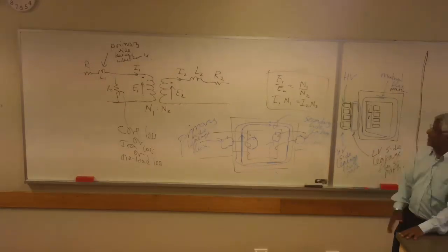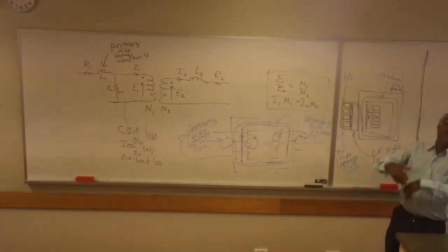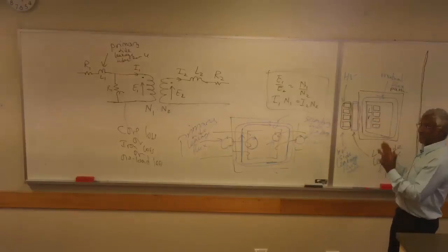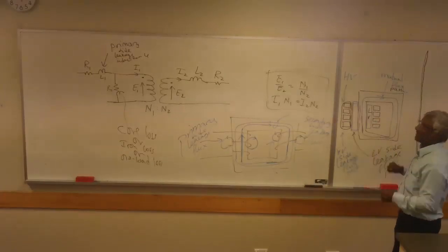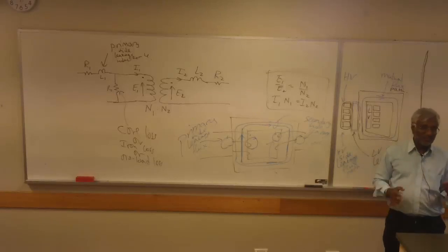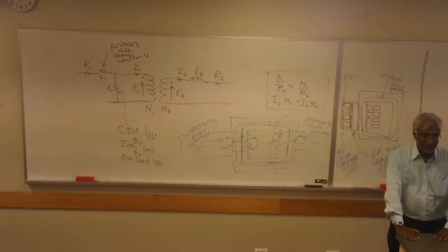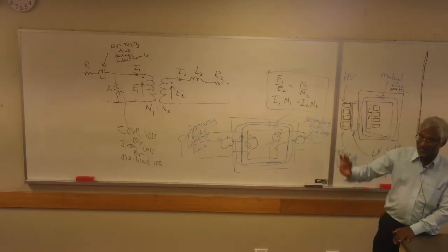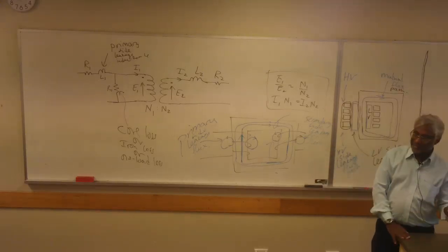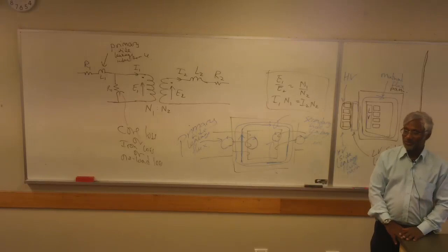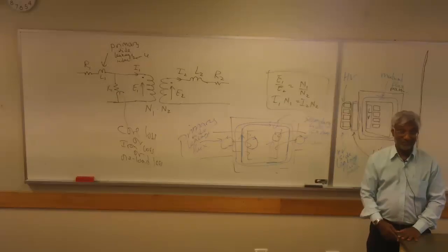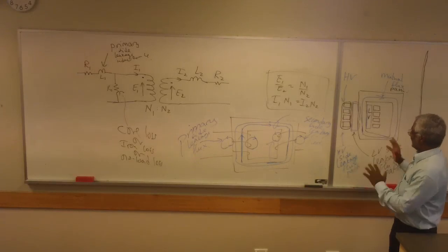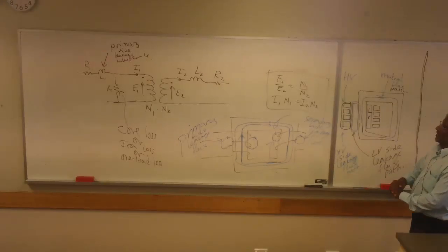Insulation, that's right. So you may have a transformer where you need so much insulation anyway that the gap between LV and HV is so big that you're getting more leakage than what you would like. Too much leakage, no good, and we'll discuss why later. Too little leakage also can be no good, and we'll discuss that later. Okay, so leakage then. We've studied leakage, I think, enough now.